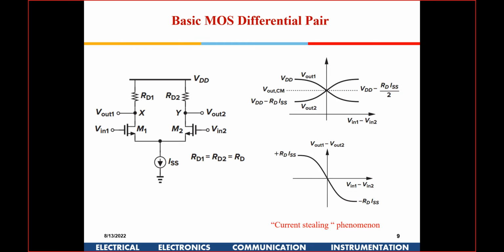And so that is what I was telling you, in saturation mode, as the current through RD1 will be constant, so there will be no change in Vout. Correct. As long as Vin and V2 are increasing equally, both are equal. Obviously RD1 is equal to RD2, and M1 has the same parameters as M2, so the width and length and all have to be the same.